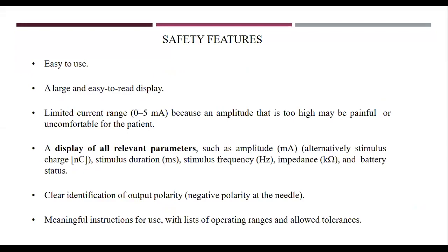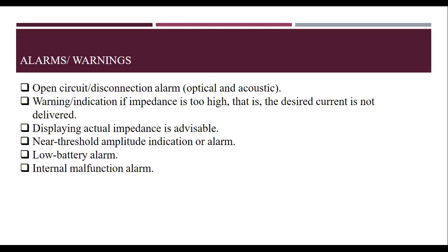Safety features are easy to use, a large and easy to read display, and limited current range, because an amplitude that is too high may be painful or uncomfortable for the patient. A display of all relevant parameters such as amplitude, charge, stimulus duration, stimulus frequency, impedance, and battery status. Clear identification of output polarity, negative polarity at the needle, and meaningful instructions for use with a list of operating ranges and allowed tolerances. Alarms or warnings.